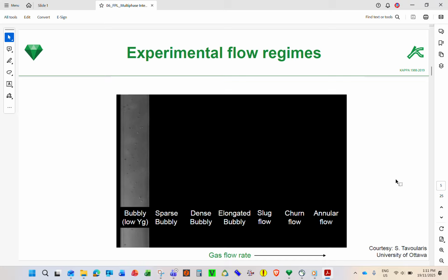So the annular flow is considered very high gas, and therefore the liquid is just on the side. So in that case, the conventional hold up tool will not detect it because the liquid is on the side. So we'll detect maybe 100% plus. So that's the possible thing.